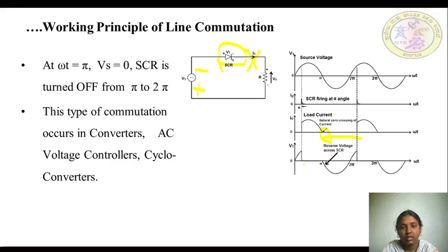So once the SCR current starts to flow, SCR will act like a switch. That is, the switch will be in the closed state and very few losses will be there. So a very small voltage drop will be there. That's all. So only during the period 0 to alpha, where the SCR is not in a conducting state, the same voltage as your source voltage will appear across your SCR.